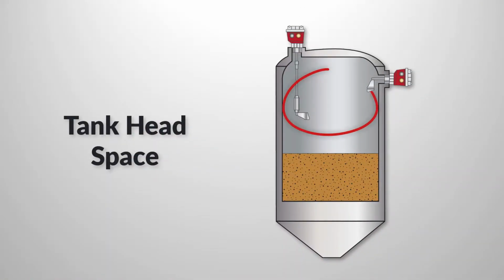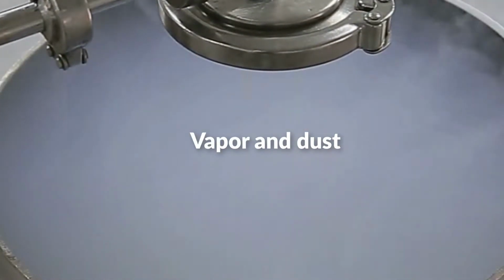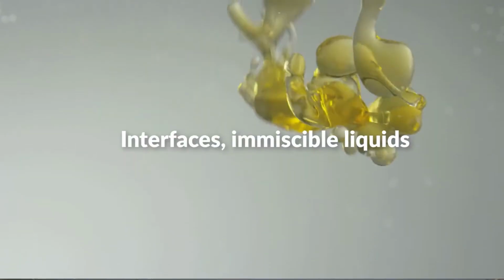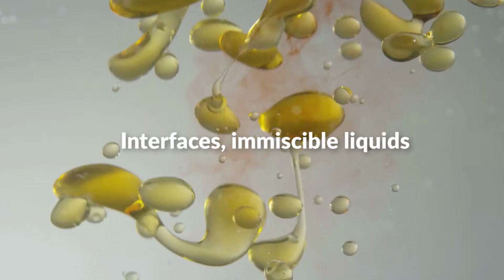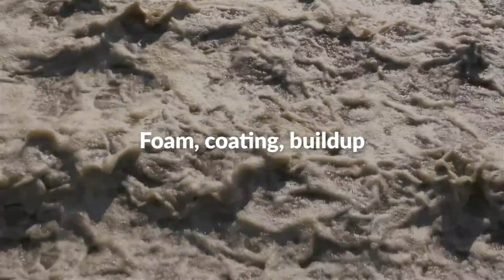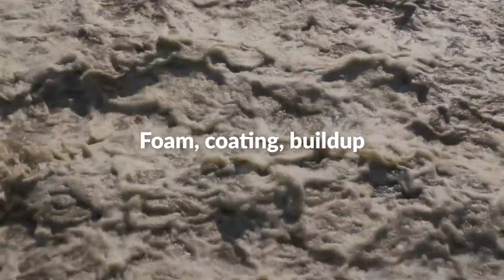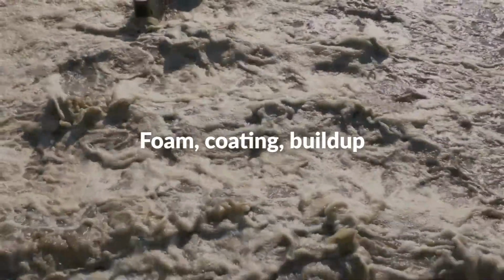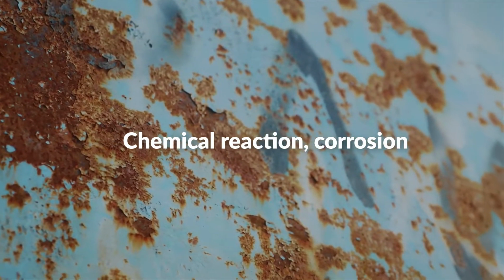A tank headspace, the space above the material, may contain vapors or dusts that obscure the view of the surface, and sometimes the level of interest is actually an interface between two immiscible liquids. Tank contents may include foam that blurs the surface. Foam or fluids may coat, build up, or solidify on the sensor. Fluids may be corrosive or react chemically with sensor materials.